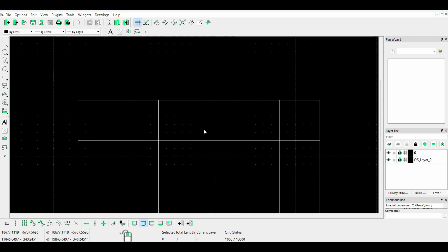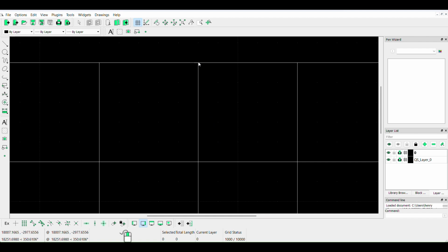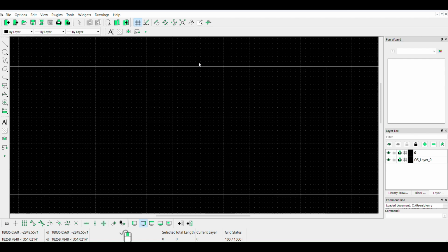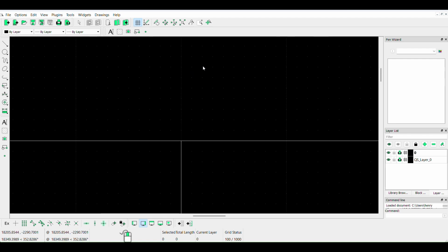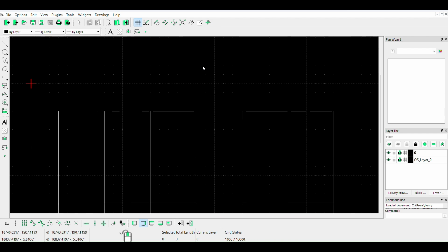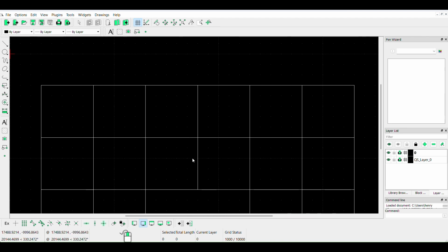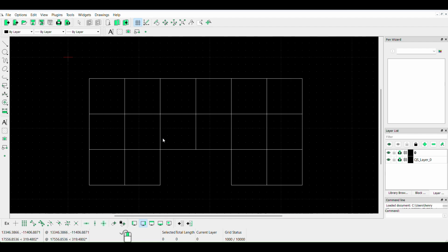If you have any gap, even a 5mm gap, the software will notice. The trouble with AutoCAD is that with a 5mm gap, you might need to zoom and zoom and zoom before you can see it. But in any case, just make sure you prevent that from happening. That is one of the reasons why, to a large extent, we advise people to model directly with our software. There are many ways you can mitigate other things that you can do, but generally, we advise people to model within our software.